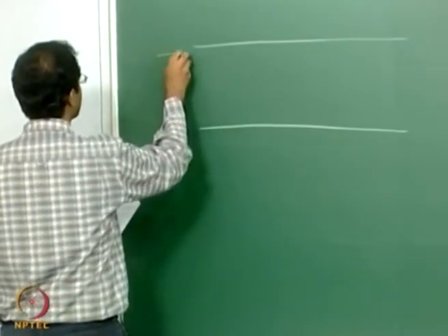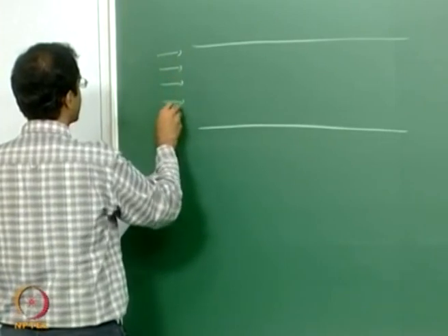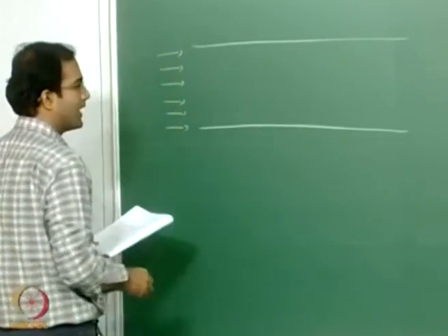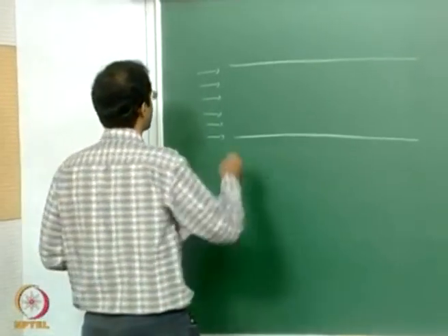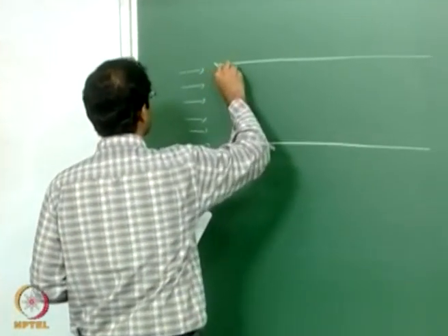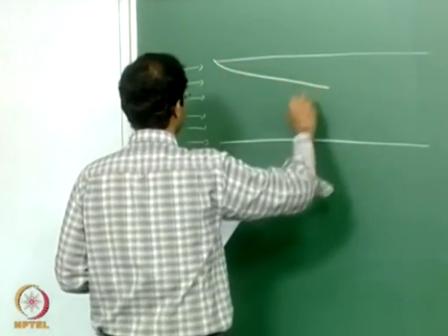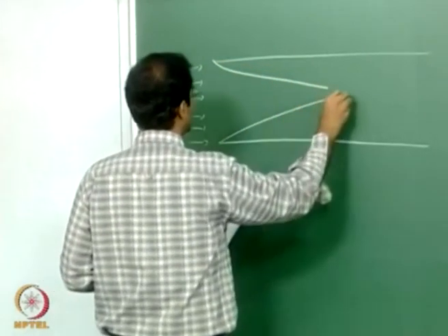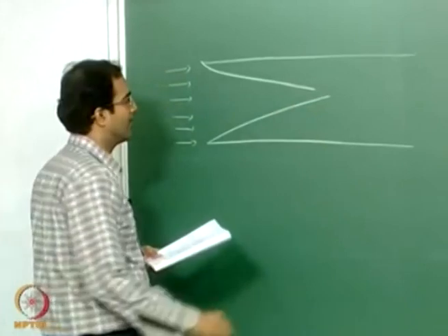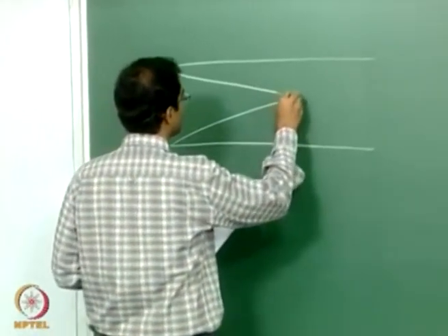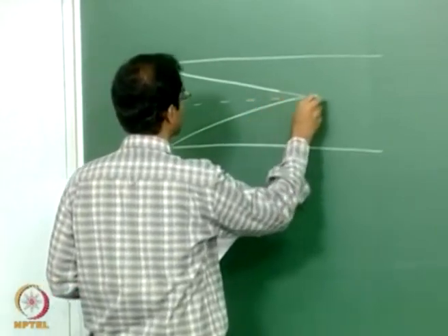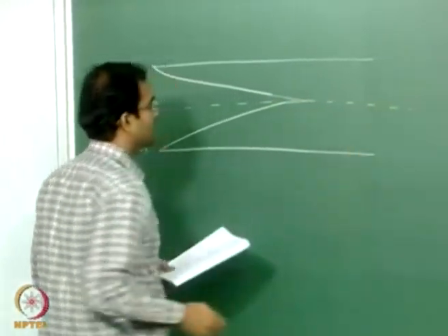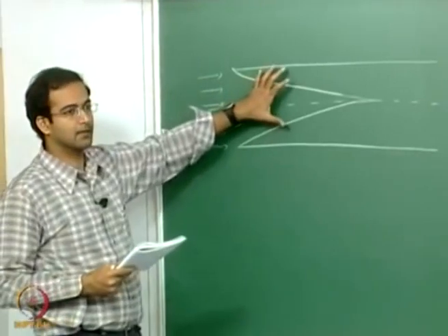So here when the flow is entering the inlet of the duct, you have a uniform velocity across the cross section, and then you see a boundary layer growth from say the two walls of the duct like this, and this growth keeps going on till a particular location which is at the center of the duct diameter.